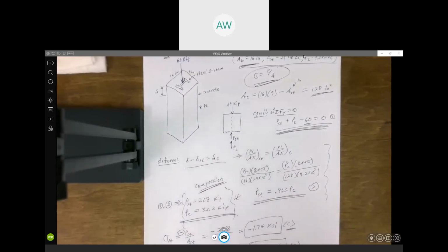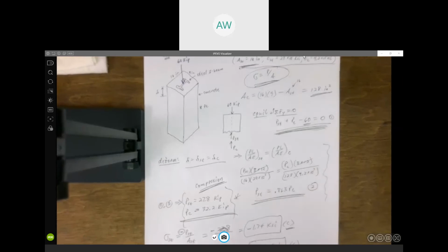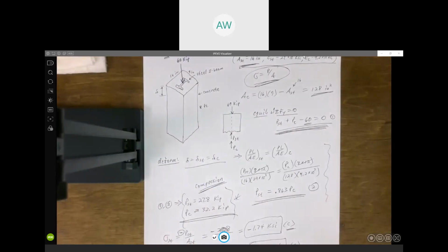That's what the steel is in there for. If you have a beam, something that's being bent, the steel is in there to take the tension load created by bending that the concrete can't take. You take pure concrete and you bend it, it's going to break because the concrete just doesn't take tension well at all. And so that's why the steel reinforces either beams or bars or whatever is in the concrete, to take the tension if it's being bent. Anyway, that's just extra information, but it's the first time we've encountered this, so I thought I'd mention it.